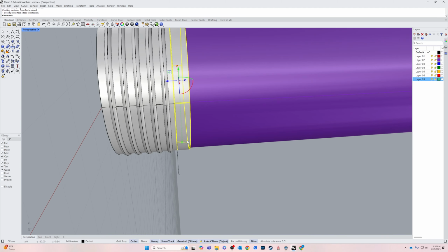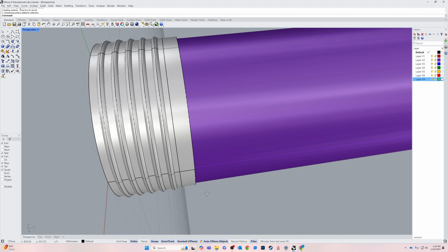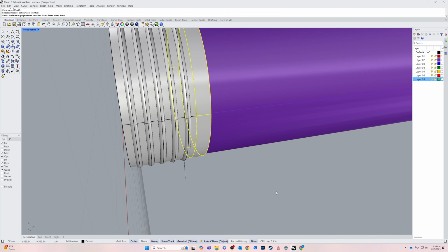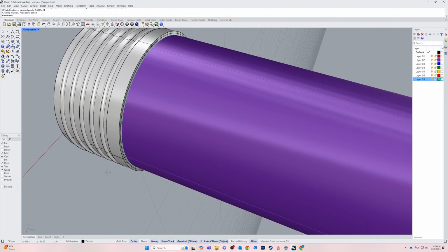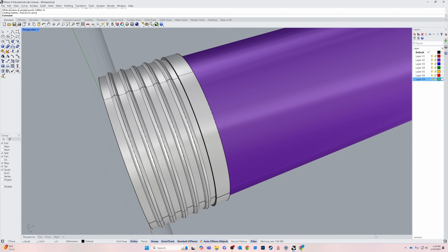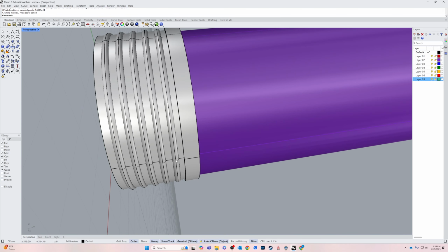So that just cut this section out. All right. And then I'm going to go offset surface, select Control Shift, click on that exterior area, enter. And then my dimension, I'm going to do 0.5, enter. Looks pretty good. Okay. So that gives me that little detail.